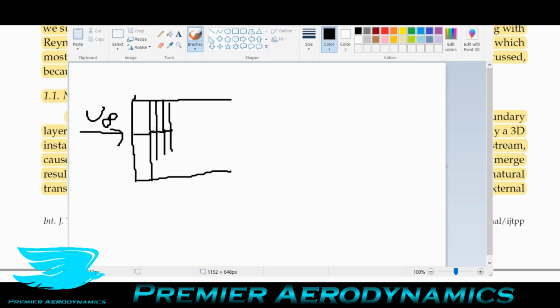So we get this two-dimensional Tollmien-Schlichting wave first. It breaks down three-dimensionally, and we start to get these hairpin vortices, as they call them, which is where a vortex wraps around in a horseshoe shape. And then they break down three-dimensionally into turbulent spots. So you have all these little turbulent spots everywhere that form: a spot here, a spot there. Then they break down even further, and these lines indicate where all this turbulence is occurring. And then finally they meet at some point, and now the entire boundary layer is turbulent. That's how this Tollmien-Schlichting mechanism works.